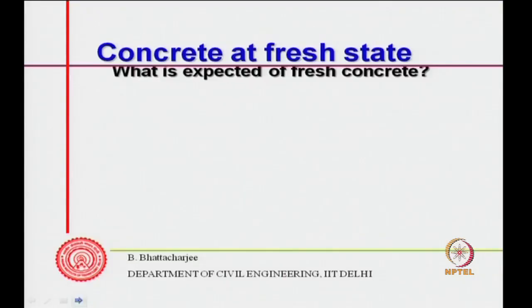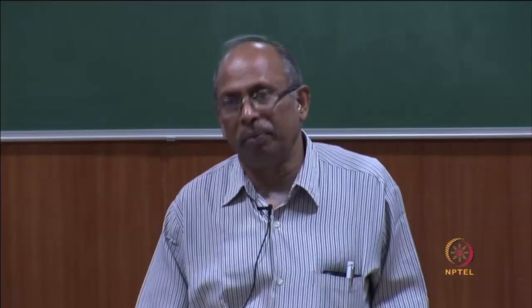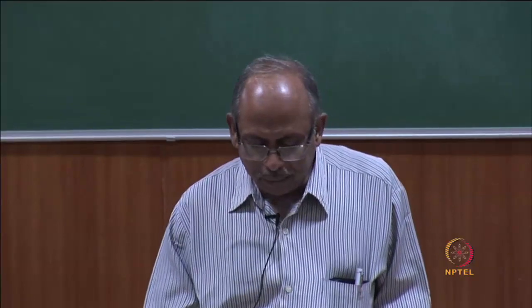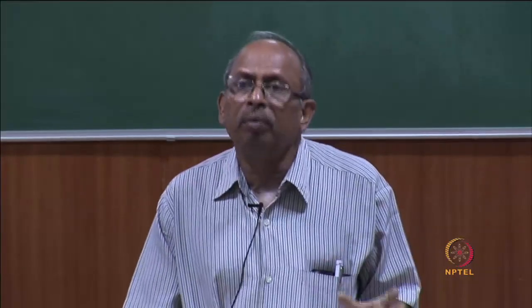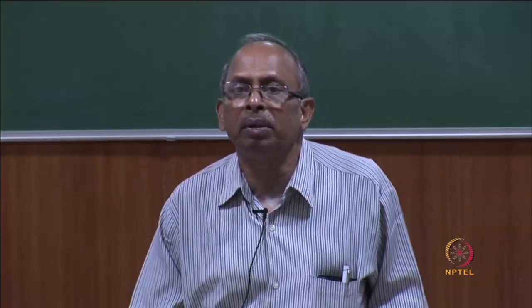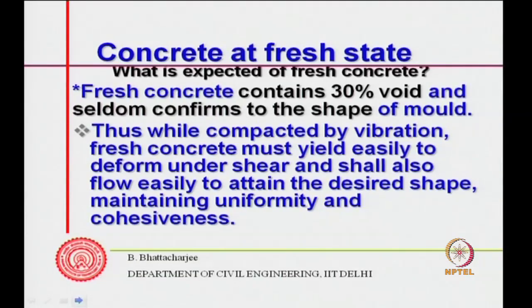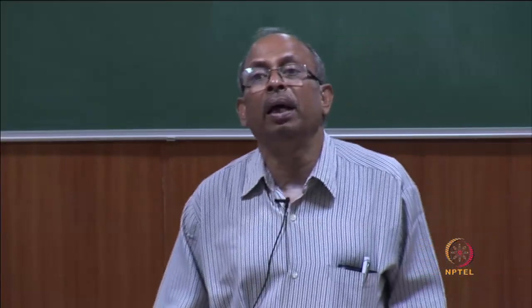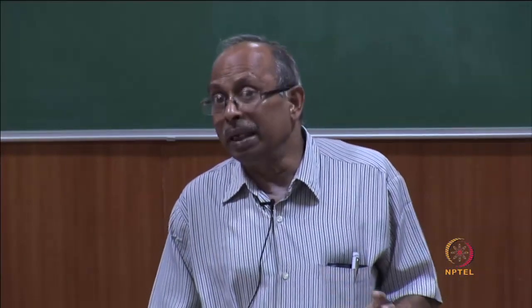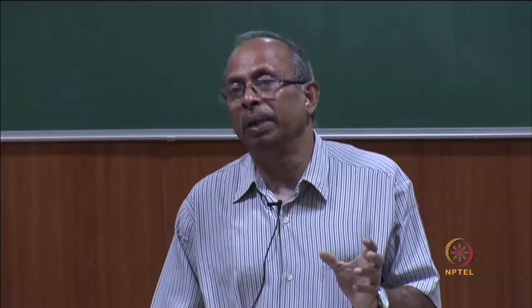But the other issue related to this is the consistency of the paste itself. To look at that, we should look at what is expected of the fresh concrete. What do we expect of the fresh concrete? Normally, I am talking of normal concrete, it will contain around 30% void, and it does not conform to the shape of the mold. So, we compact it by vibration, and when you are compacting with vibration, it stands in a heap. So, it must yield easily and deform under shear, and shall also flow easily to attain the desired shape. But at the same time, it must maintain its uniformity and cohesiveness.